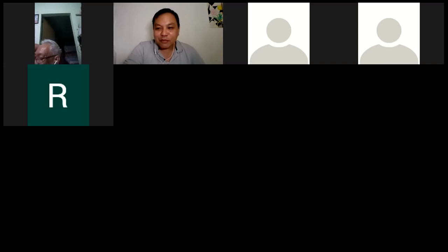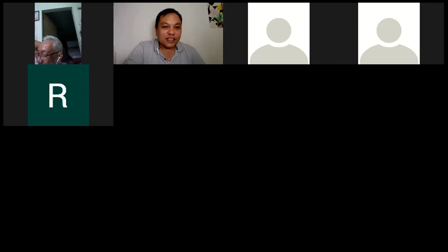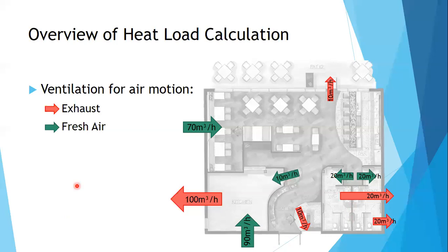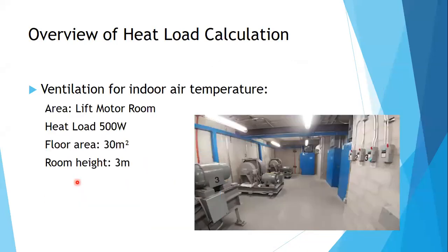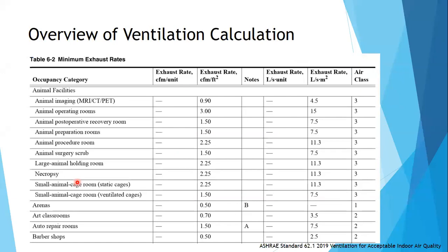Earlier, let me share my screen again. Share screen. This one. All right. Spaces is mentioned in 2 areas. First, table 6.2, meaning these usually are ventilated areas lang. They need to have a negative space, or a negative air pressure. So this one, they have minimum exhaust rates.